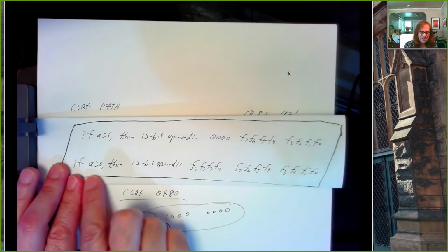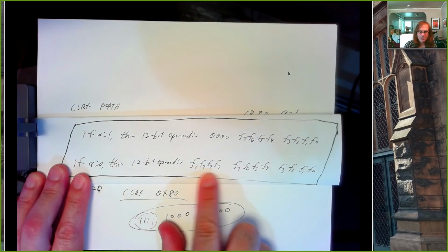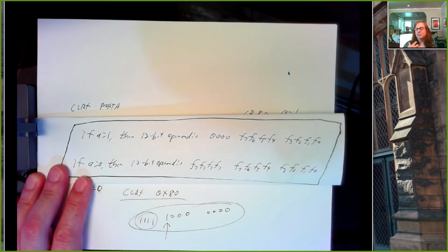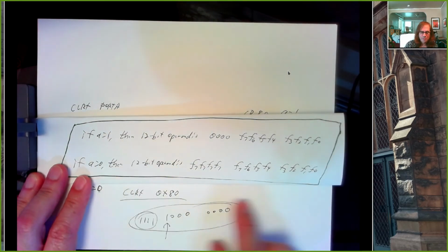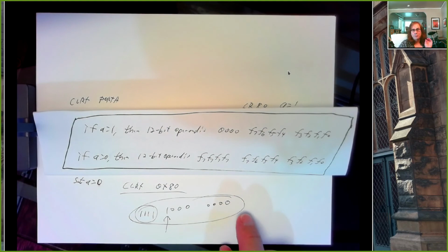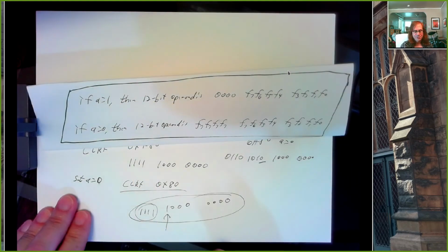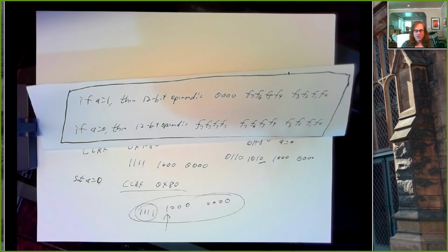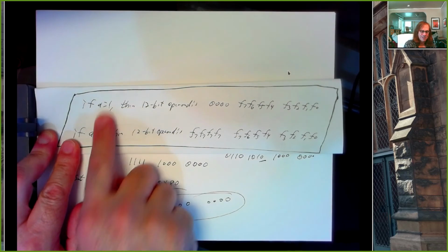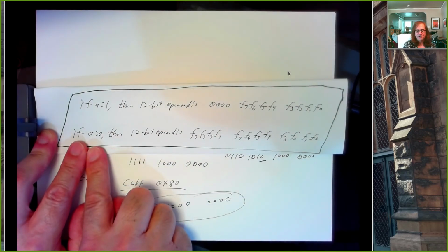Because if we set the access bit to 0, we're going to end up with a bunch of 1s here. And if we're using a general purpose file register, set the access bit to 1. That will work, but it's a little more complicated than that. If we go in the other direction, if we have binary for an instruction and we want to know what that instruction is doing, then we need to actually understand exactly what the access bit is doing.